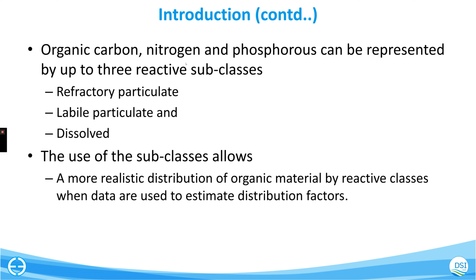This is basically what's known as the ICM kinetic model. It was developed by the Corps of Engineers many years ago for the Chesapeake Bay by Carl Cerco and others. It's widely used. It's used in the CE-QUAL-W2 model, in EFDC Plus, and I think they've got modules for CH3D that are linked up at the core. Different hydrodynamic models have been coupled with this module, and it works well.